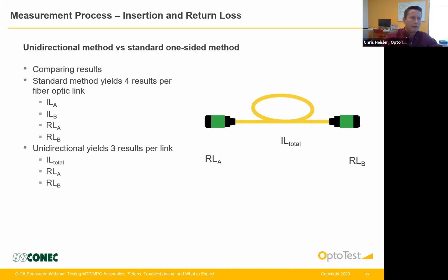If during referencing you had a bend or some dirt on a connector, and that dirt or bend was removed during the measurement process, that would also potentially give negative IL values.